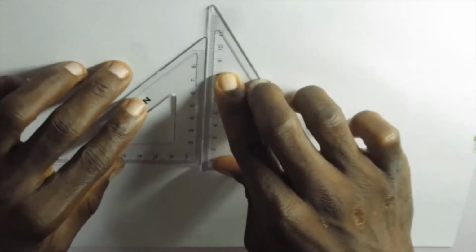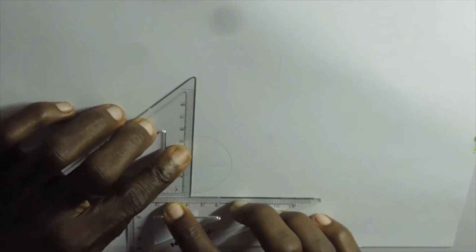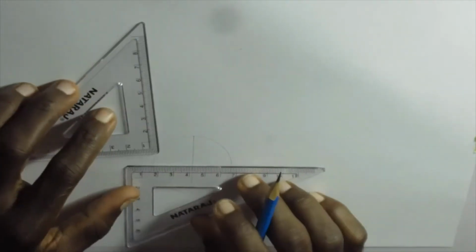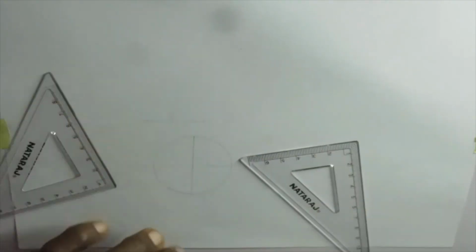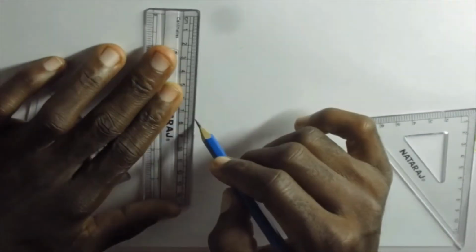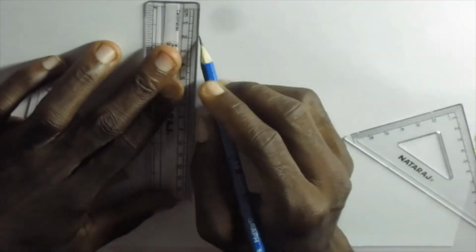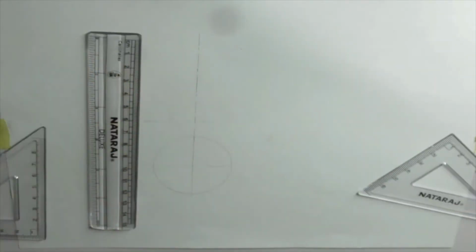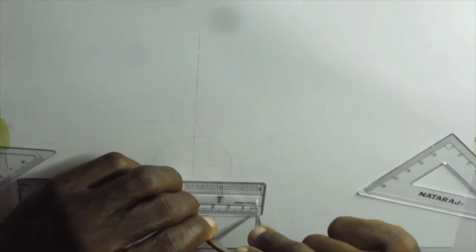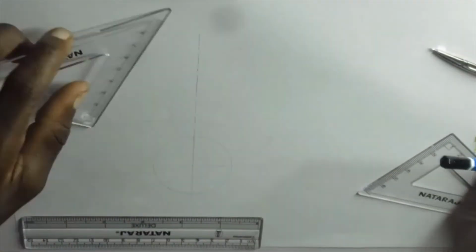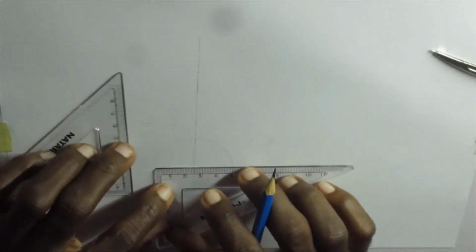So we first need to draw the orthographic projections of the cone, which include the plan and the front view. And the front view of a cone is a triangle, and the plan is in the form of a circle. So we draw the circle, which is the base of the cone. Then from there we draw the front view. All right, so front view, we draw it, and to determine the slanted edges of the triangle on the front view, we have to project from the base circle.